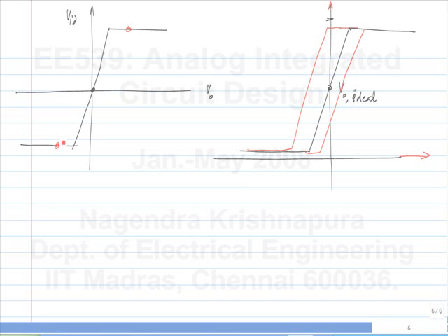But what happens if I am operating around this point? It's not behaving like an amplifier. I wanted a certain characteristic from the op-amp, a certain transfer function. That was a high DC gain, and the high DC gain is in this range. Every circuit in reality is not linear, I only approximate it by linear systems. So I have to bias it somewhere within this range for it to provide high DC gain. If it is biased somewhere here, it is clearly not an op-amp. It's useless for use in a negative feedback system.